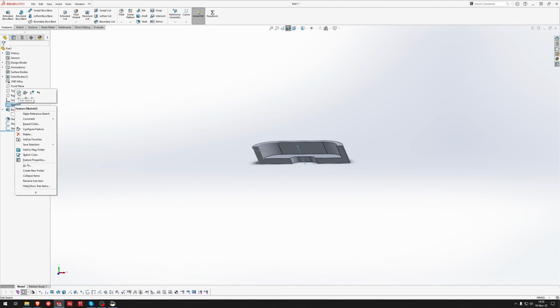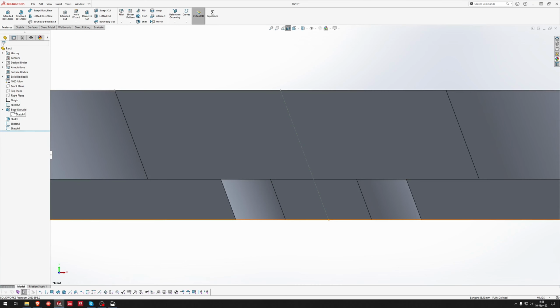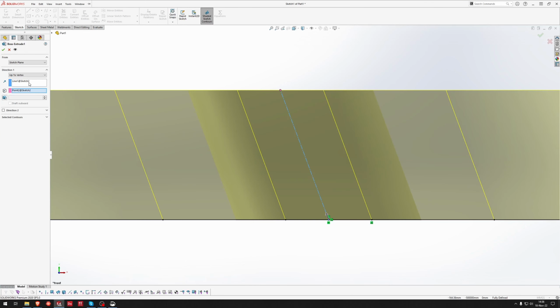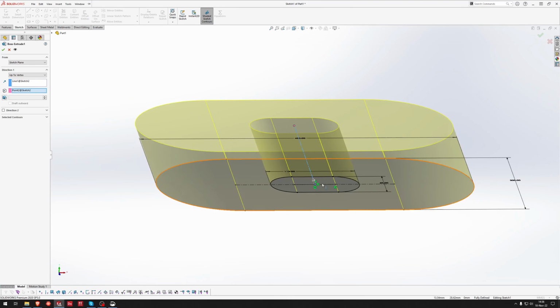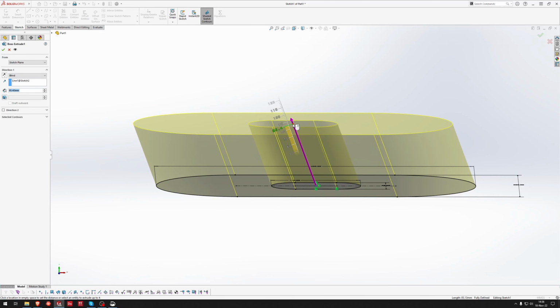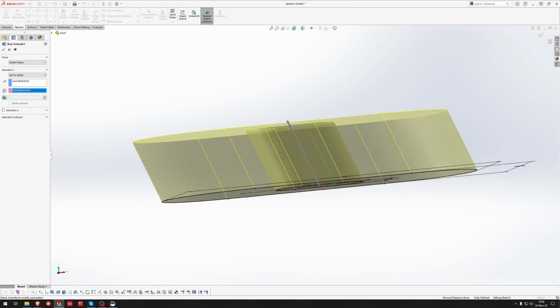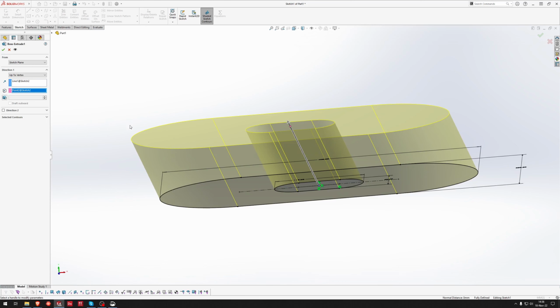And then we did this direction sketch from the side, which is an 80 millimeter tall, just to define the height of the extrusion, and then our angle right there within our boss extrude feature. This box here shows the direction of the extrusion, so normally this is just normal to your sketch plane, just straight up from there. But if you have another line that can define it, you can use that instead. And then we did an up to vertex end condition rather than creating a plane. We just went right up to that point, and it was a lot simpler because we're already defining a line that's going in a particular direction.